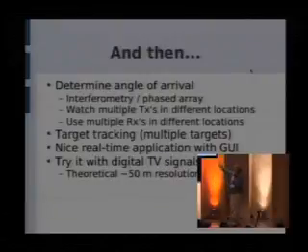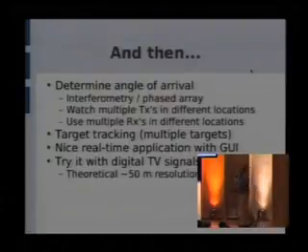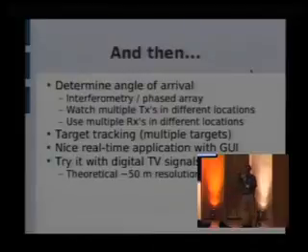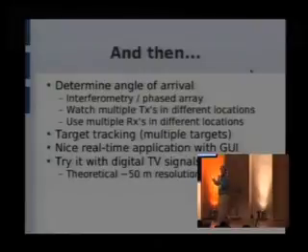And then when this is all working, we'll have the white paper out that says, order this thing, then you build this antenna, and then you run this free software. Then the next thing we do is probably do it all over again with digital TV signals. The cool thing about digital TV signals, because of their bandwidth, is we should be able to get fixes that are within like 50 meters. If you remember back to the FM, we get 3 kilometers, which is okay. I'm not arguing it. It's better than 0, right? But 50 meters is very exciting.